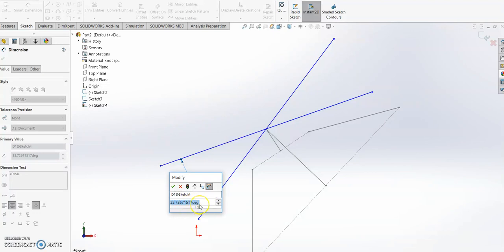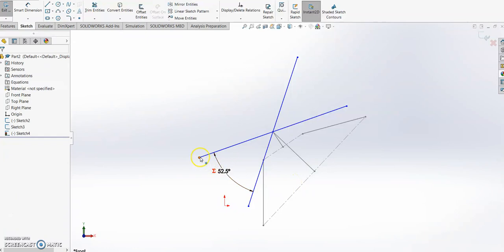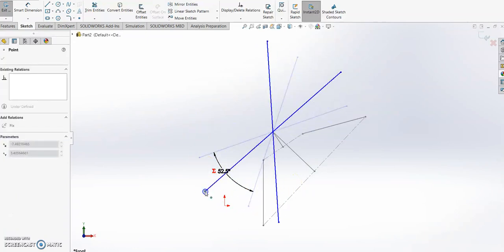This angle, we're going to define as equal to what we copied earlier, the dimension of our rotation. It's from here, our first position, rotating up to our second. Now we want to remember what direction we're referring to, as we're looking at this in the counterclockwise direction, that's going to matter. Now we can say that angle, and we're going to divide that by 2, and constrain it to be just like that. So now we have this set of angles that we can rotate and move.